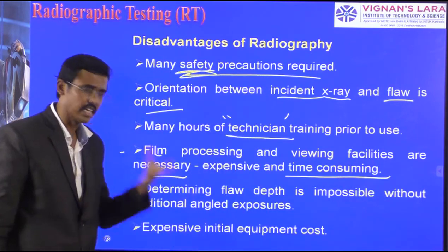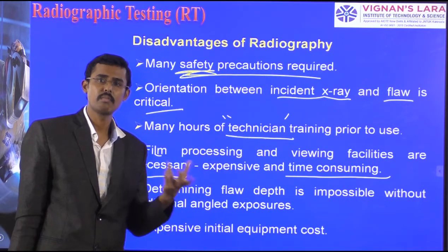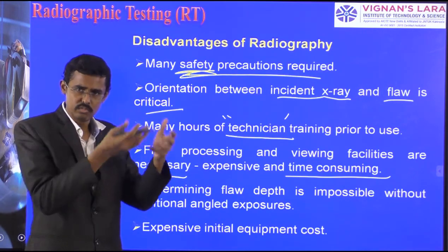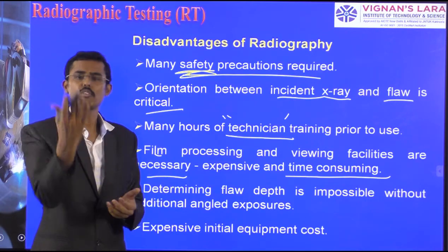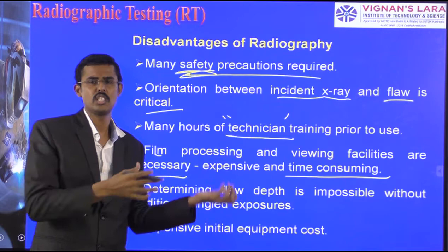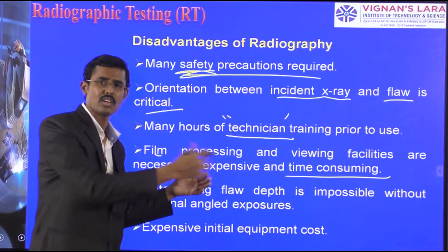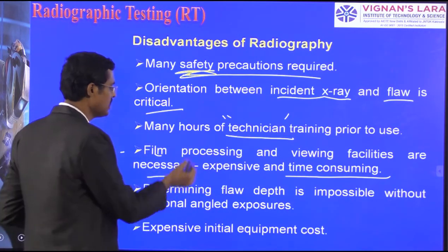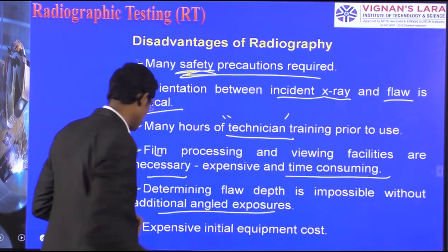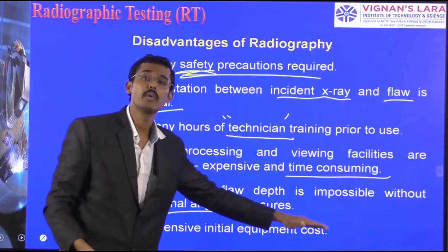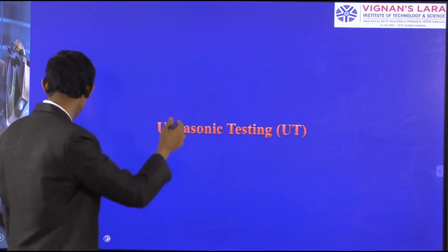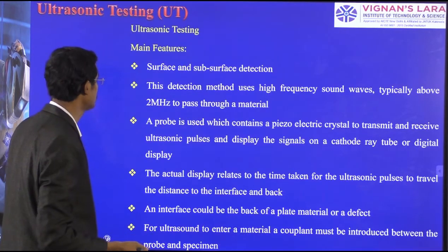By visual inspection we can tell immediately that a defect is there, but this film you have to clean and process, and the next day wait for drying, and only then can we examine the film. It is like our human X-ray taking and waiting. Nowadays digital has come, but it is still time consuming. Determining the flaw depths is impossible without additional angled exposures. The initial equipment cost of radiography is high. So next are the ultrasonic testing methods.